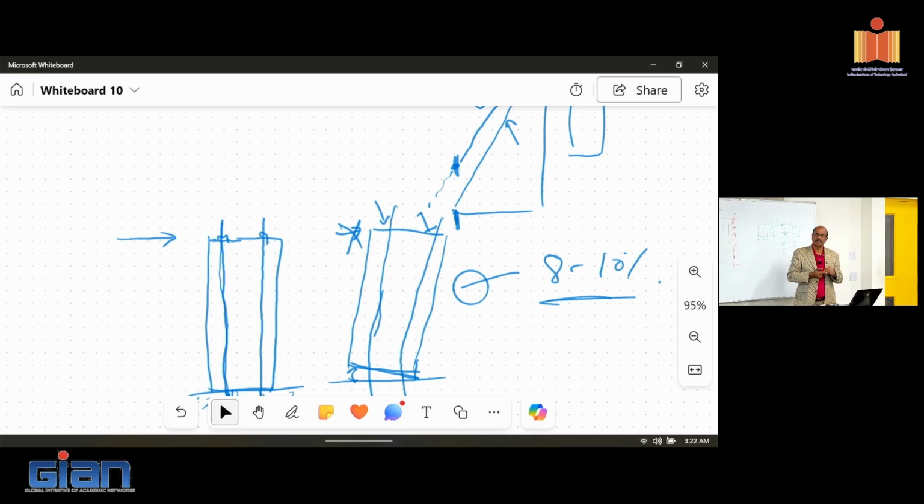We also worked with the company to show that the wedge anchorages are good, but when they release it, it comes and cuts into the strands a little bit. So the strand is getting crushed locally, failing, and getting snapped. If you know of a good manufacturer who can do a different shape strand or anchorage, we can actually avoid that problem. In fact, we worked with one company, then they got sold to somebody else, funding ran out, and we moved on. But there was information published on how it should be modified.